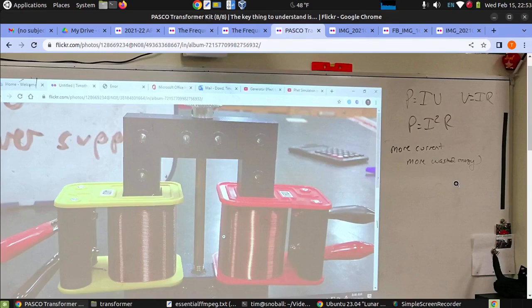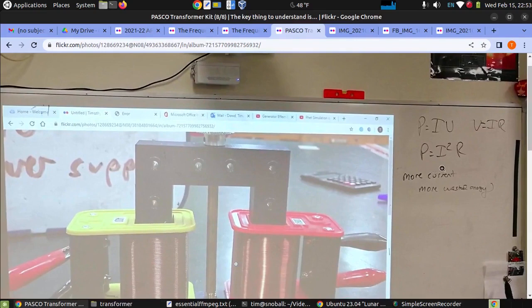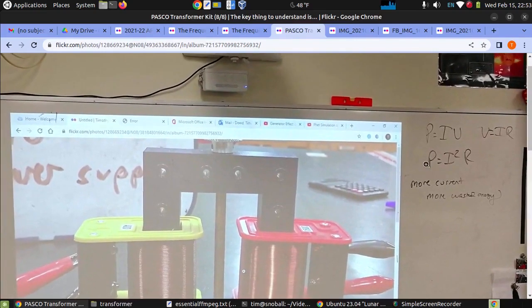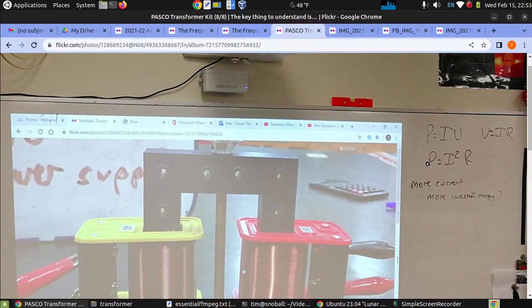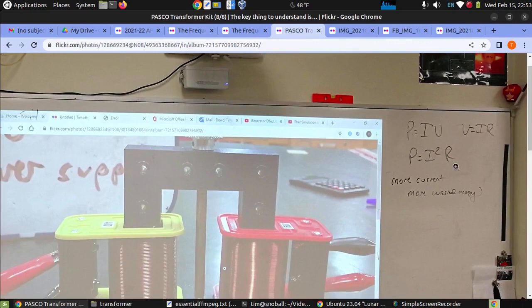Turns out that the economic importance of that question cannot be overstated. If we take Ohm's law and plug it into P equals IV, we get the equation P equals I squared R. The rate at which energy is dissipated as heat depends on current and resistance. Or in other words, anything that has resistance, if you pass a current through it, is going to create heat. And there's a quadratic relationship between the current and how quickly it dissipates heat. We've talked about this equation as the reason why we need circuit breakers. If that heat's dissipated in your house walls, it could burn your house down.